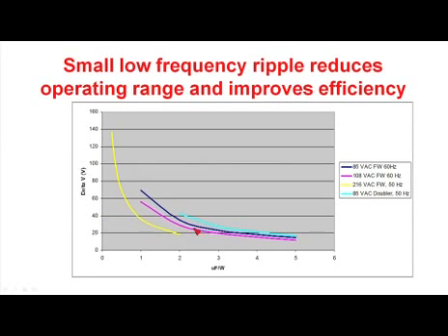The larger that you can make the capacitor, the smaller the change in voltage on the cap is, and the more efficient the power supply will be. You can see that a typical value of capacitance that you might be working with is in the range of 2 to 3 microfarads per watt.